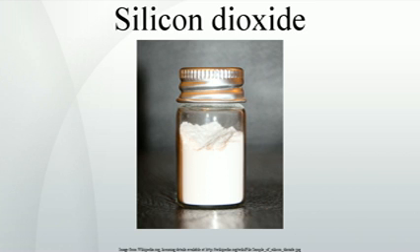The difference between the glass and the crystalline forms arises from the connectivity of these tetrahedral units. Although there is no long-range periodicity in the glassy network, there remains significant ordering at length scales well beyond the SiO bond length. One example of this ordering is found in the preference of the network to form rings of 6 tetrahedra. The glass transition temperature of pure SiO2 is about 1475 K.